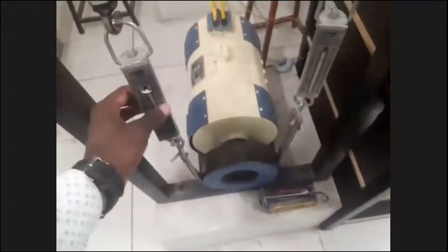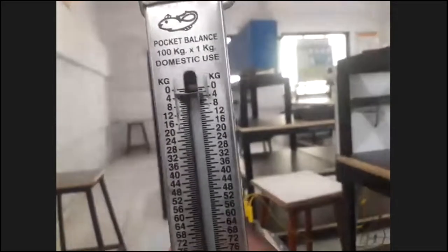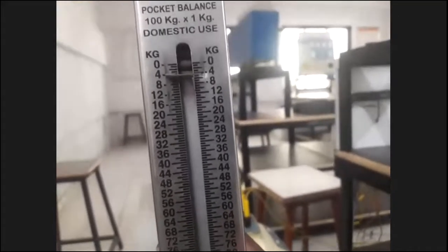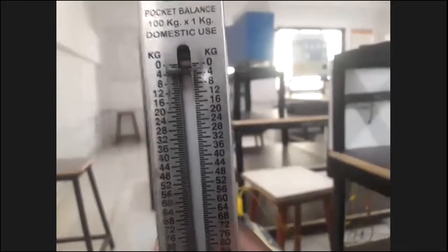So see, the mechanical loading arrangement is there; by rotating this wheel we are applying force on that drum. Drum वरती force apply करतोय. At that situation, this spring balance will show some reading in kg. Okay, कशामध्ये reading आहे, दिसतायत का सगळ्यांना? kg मध्ये आहेत बघा. So this reading is in kg, 0.48.